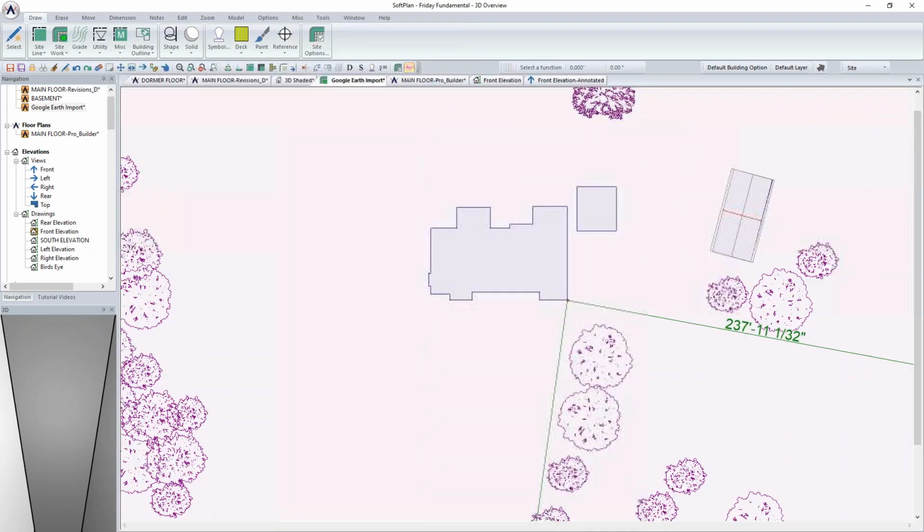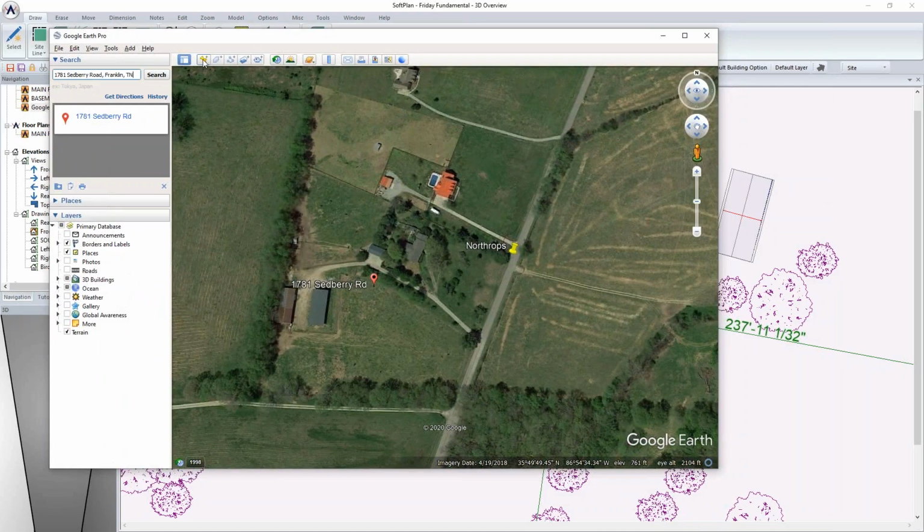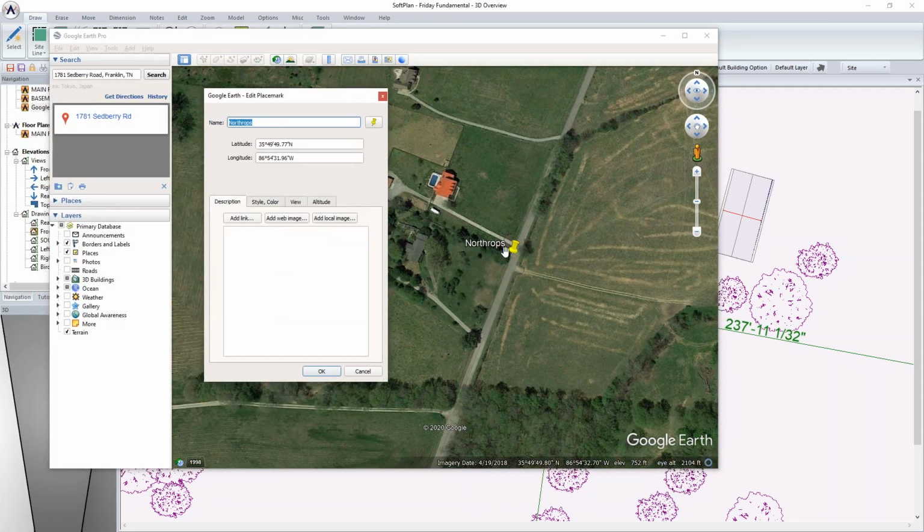The key here is at this stage, I have dragged and dropped the point onto the drawing so that when I edit this, which is the front corner, I can actually pull from this the properties that go with the place mark. I already had one on here, but it was just drag and drop to place the place mark, and then I right click and grab this information right here. This is going to be key for me in just a moment.